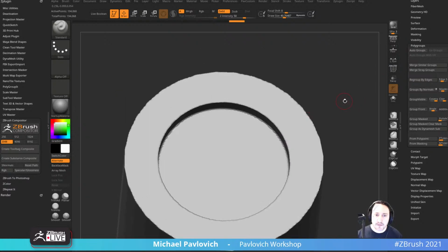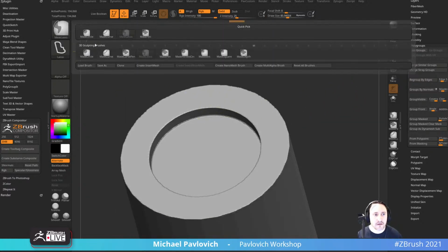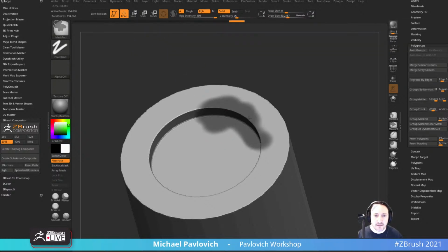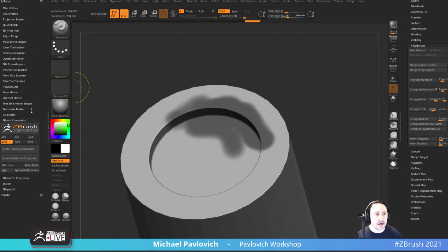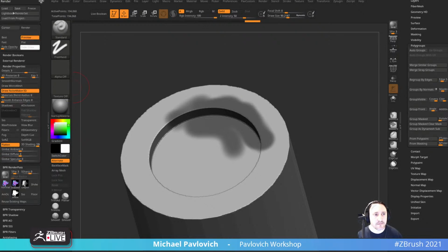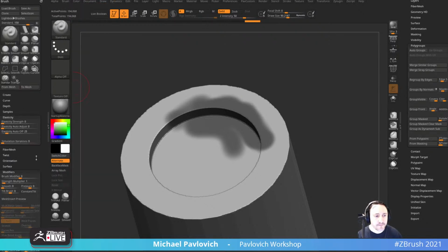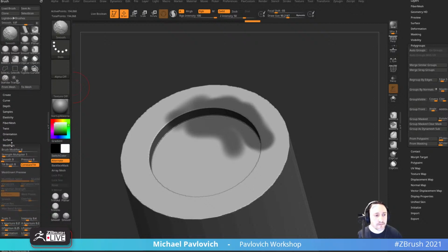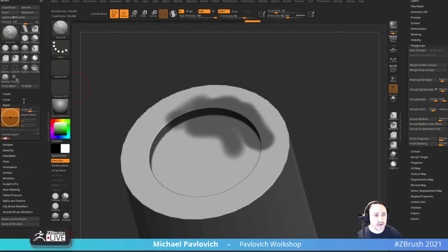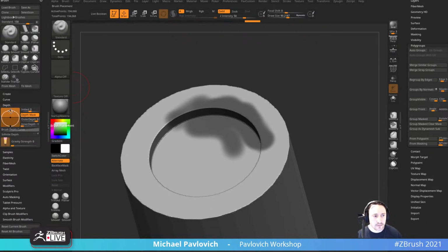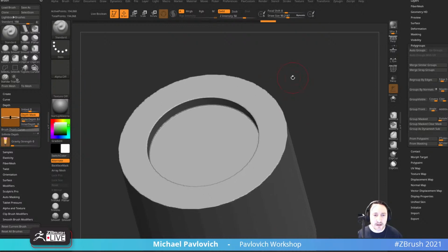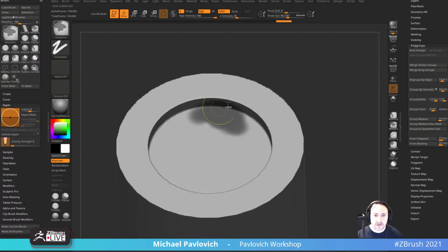So we've got this mesh here, and we want to use masking here. So we'll go in here to mask pin. So masking by pin is just going to mask literally what's on your screen. Under your brush settings, however, we can do depth. And then in here, turn on depth mask and just pull this top one down, not all the way to 0, but to a very low value. And then this one, not all the way to 0, but a very low value. And now, depending on where you start, it should stop.